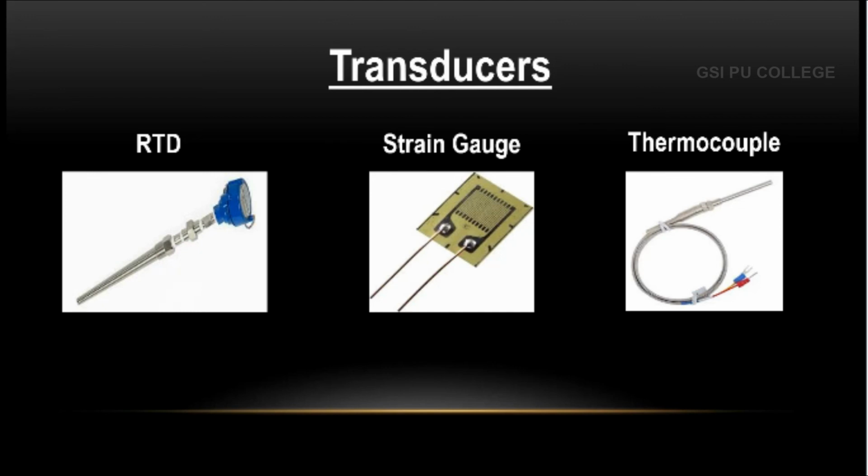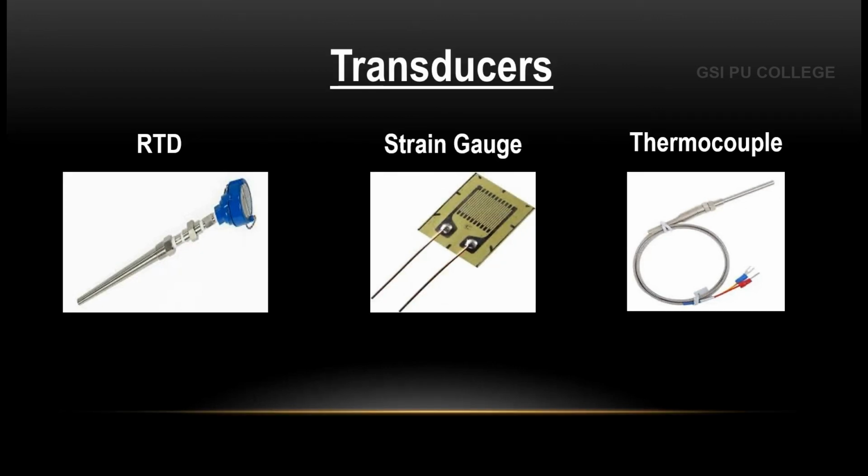So, long connecting wires or cables are required in such a case to get the transducer output to the control room. Due to this, the signal, which itself is very low, gets subjected to noise and atmospheric interference. Hence, it is necessary to amplify the level of such signals, rejecting the noise and the interference. The amplifiers must have high common mode rejection ratio, that is CMRR. Hence, a special type of amplifier is used, which is called the instrumentation amplifier.